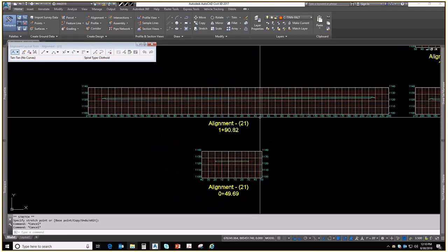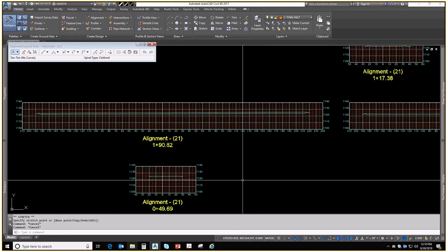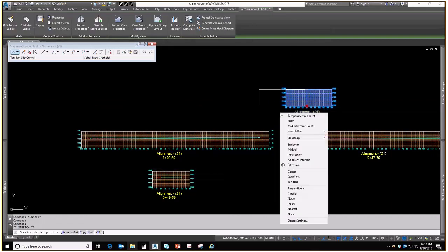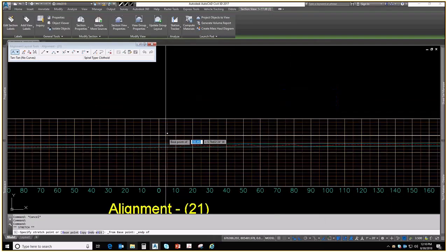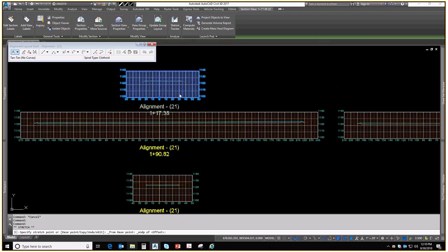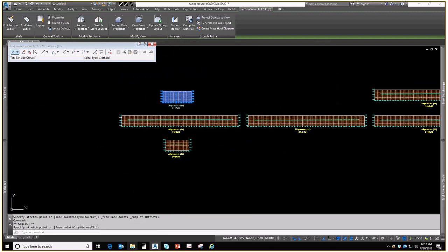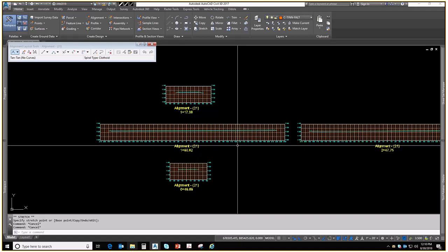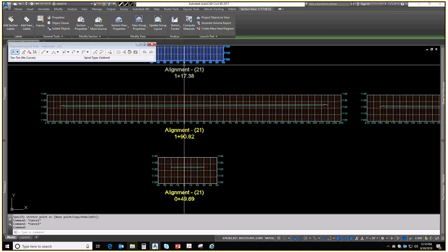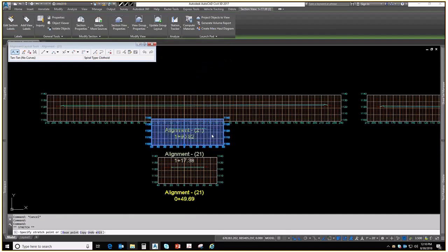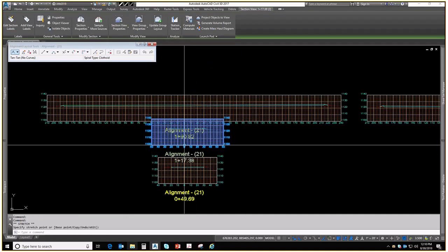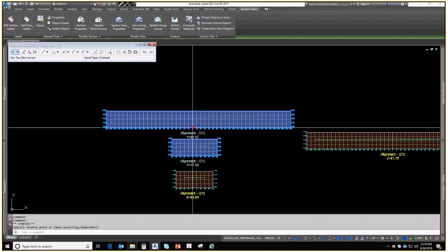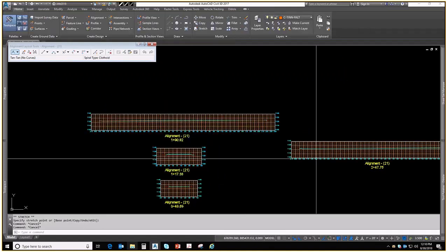And just to comment on, Joe mentioned whether or not you're putting cross sections on the plans. Different clients have different requirements. Different consulting firms and practices have different standard practices. But if we have significant quantities of earthwork and we are measuring earthwork on a unit price in the project, we like to put earthwork quantities in the plans. And what that does, it establishes a basis for the contractor to verify our numbers against theirs, because they can see what our numbers are based on.